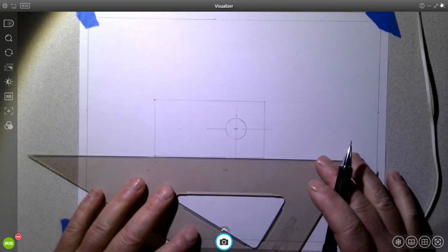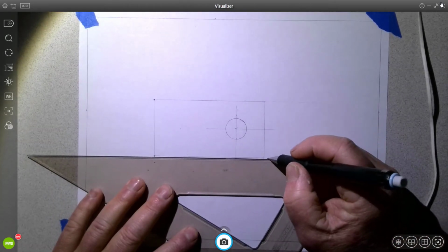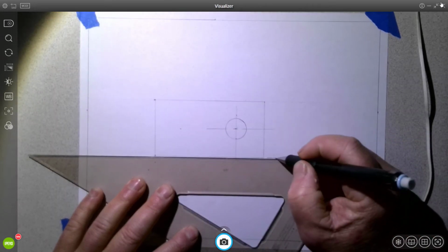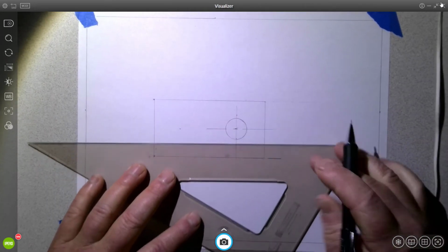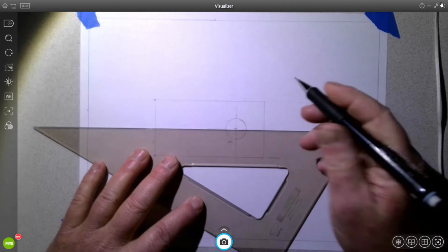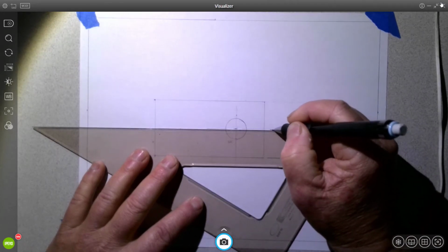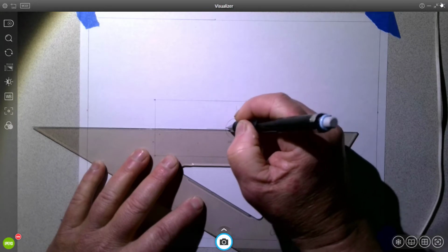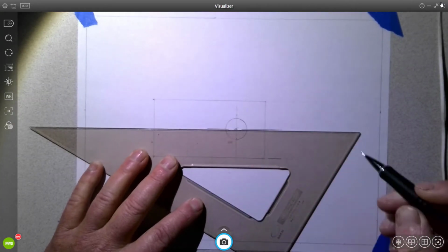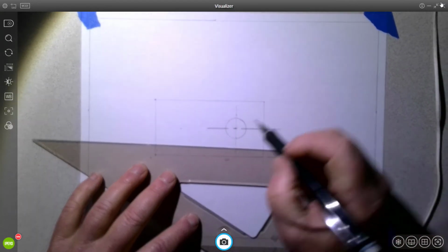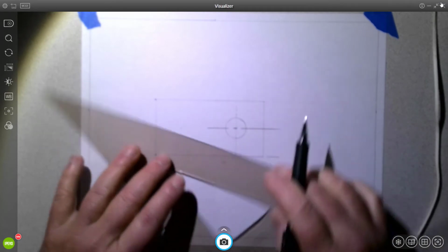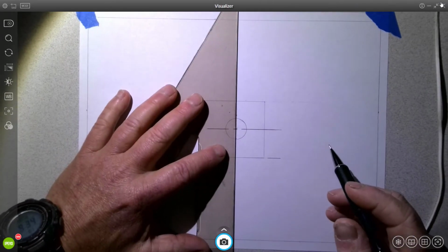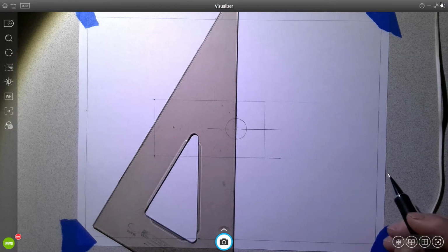So I'm going to pull off the bottom, and remember your extension line has a gap. But if you're using a center line, which you can, it does not have a gap. And the center line is a long, a short, and a long. And it always goes past whatever it's marking. So this extension, like if I didn't use it in this direction, oh, that's really difficult.